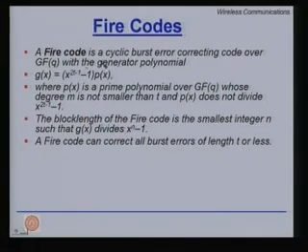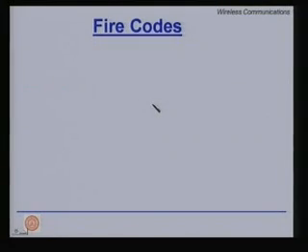So, within the definition of the generator polynomial, I have put in how many burst errors I can correct. So, I have a design rule here. I fit in a value of t. If it is 3, you have x raised to the power 2 into 3, 6, minus 1, 5, x raised to the power 5 minus 1 times p(x), where p(x) must satisfy this property. p(x) does not divide x raised to the power 5 minus 1.